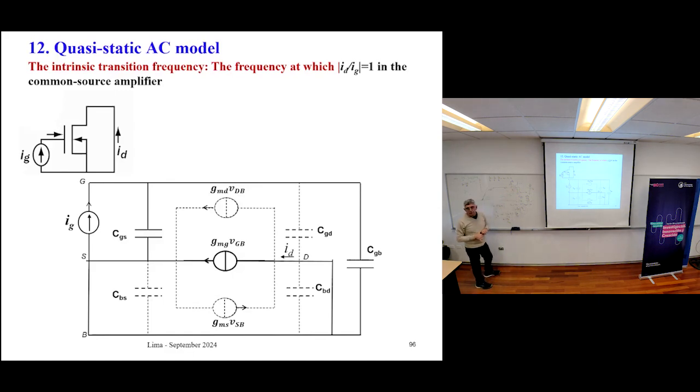capacitor. But of course, you need frequency here. Otherwise, all the current will flow through the resistance. So let's say this would be acceptable for frequency, high frequencies, or for frequencies in which this impedance is much lower than this one. Okay, so you need something here.